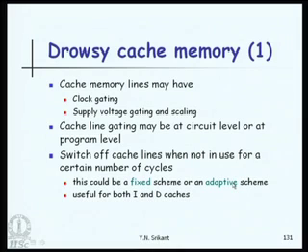So, in other words, we just check whether the cache line has not been in use for a fixed number of cycles and then switch it off, right. Otherwise, it is also possible to take an adaptive stand, thereby saying okay, let me not fix the time duration once for all, but it will vary based on the program. So, that is an adaptive scheme. It could become smaller or larger, and it can be used both for instruction and data caches.